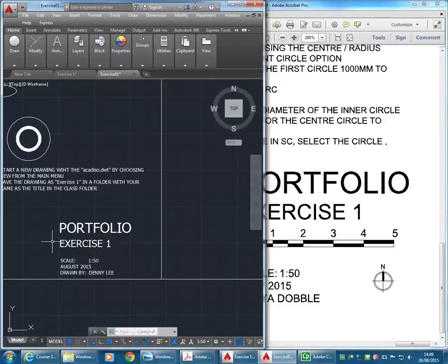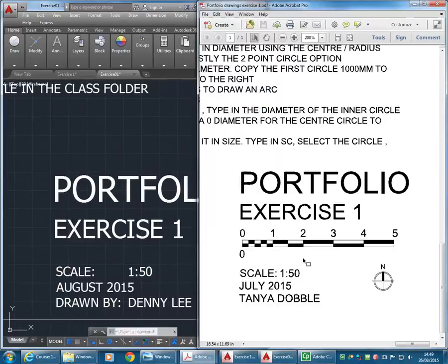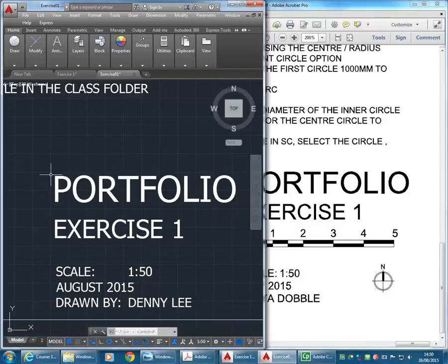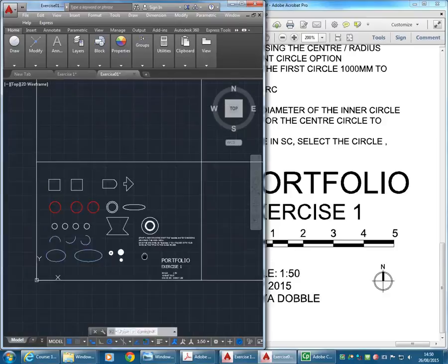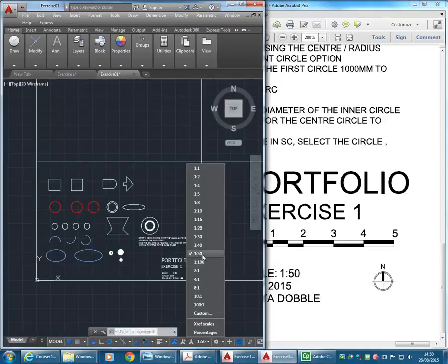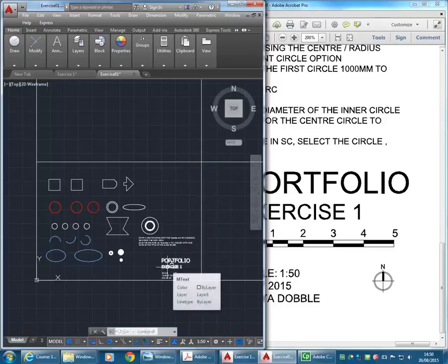And so then, finally, maybe just to make it clearer when you are working at different scales, how scale actually works in a CAD program. You can see here you've got this scale bar. So notice it's got measurements, and they should all be in metres, or they should all represent a metre. So when you're drawing in a CAD program, you are setting a scale. So remember, I've set 1 to 50 as my scale here. But as I've been saying, that only affects things like text, and you'll see in a moment dimensions.